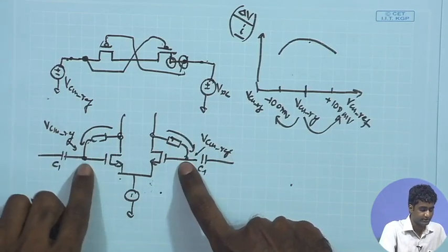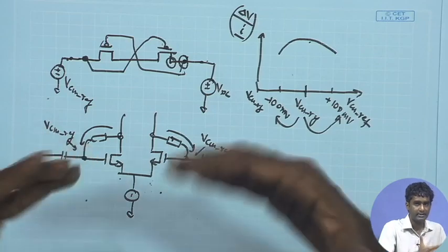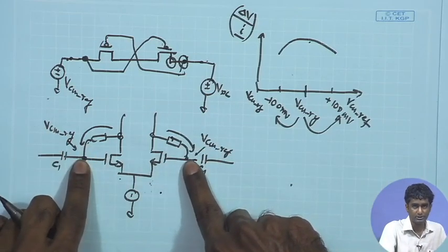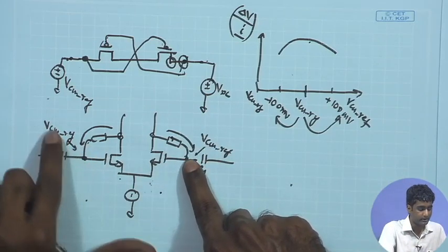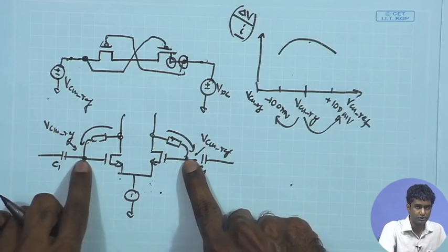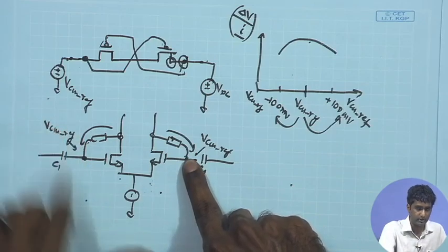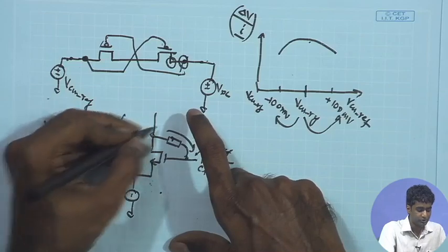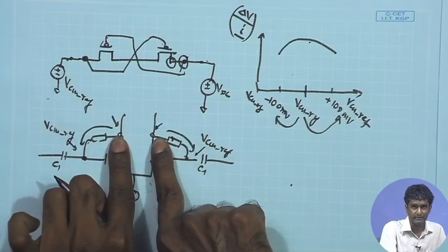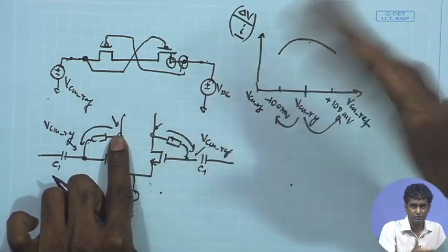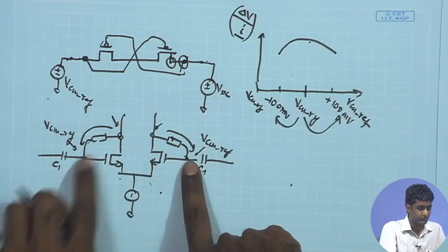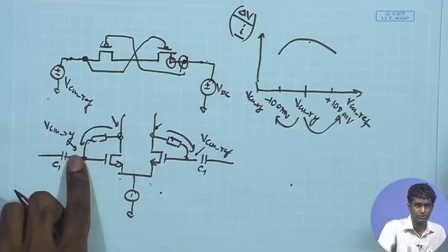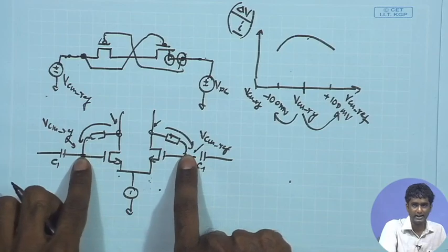You are initializing this potential. That means, rather than starting with a random DC potential, the simulator will start by putting these two potentials at the VCM ref, and since these two potentials are anyway quickly set to the VCM ref by the help of common mode feedback, which is going to operate much faster, it will ensure that in the long run also, as your simulation goes on, this potential is maintained at VCM ref.